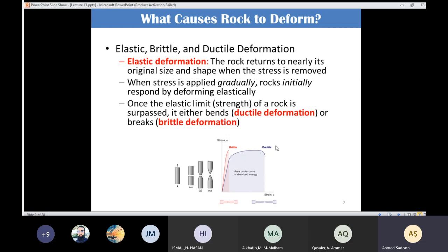And this one is illustrated by that necking here. So if I'm going to have large deformation compared with the stresses after the material reaches maximum capacity, we are going to say that we have ductile deformation. And if you have sudden failure like this one, without showing large deformation before failure, we are going to say that we are having brittle deformation.